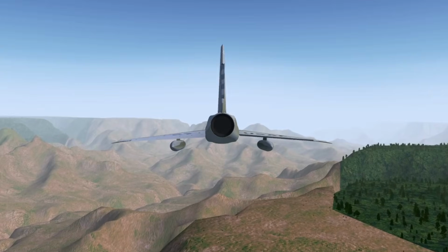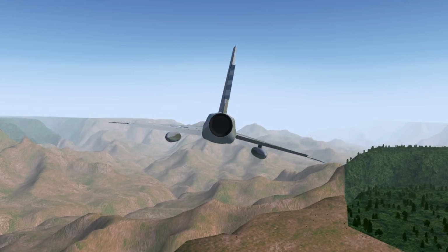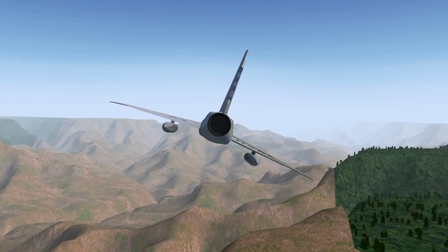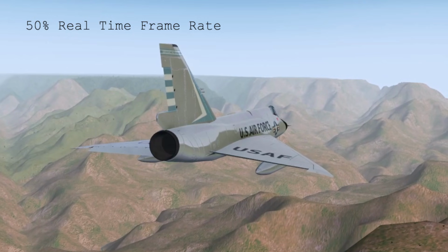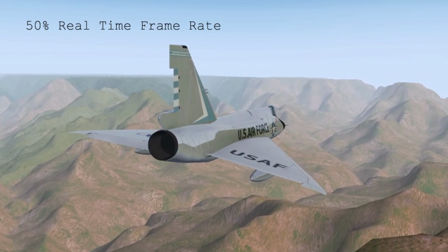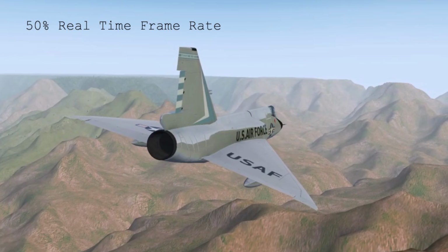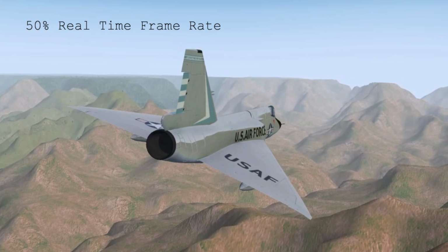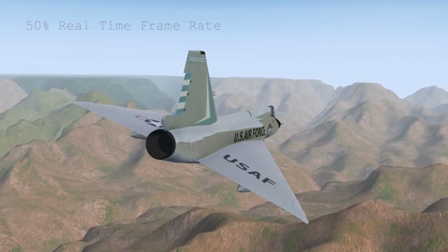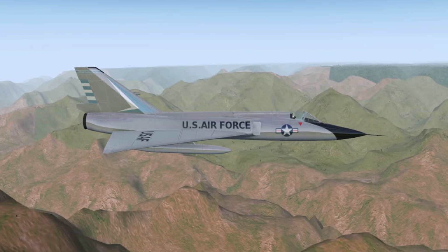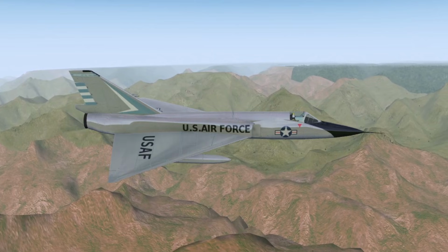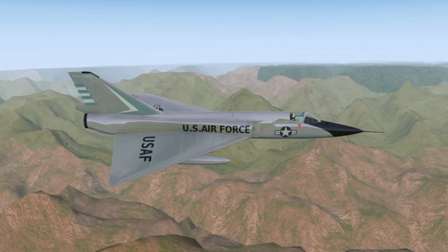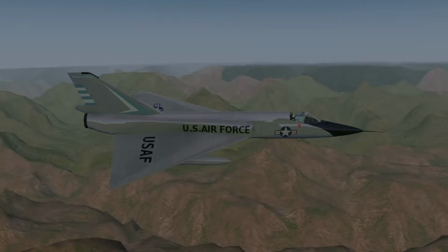Now, the simulation visualized with the F-106 aircraft. To achieve the turn, there are brief transients in the control surface deflection. Then the aircraft achieves a steady state turn as desired. The pilot would struggle to compete with the rate that this tuned automatic control system achieved a coordinated turn. However, with this system, the pilot can have excellent turn performance while focusing on other tasks.